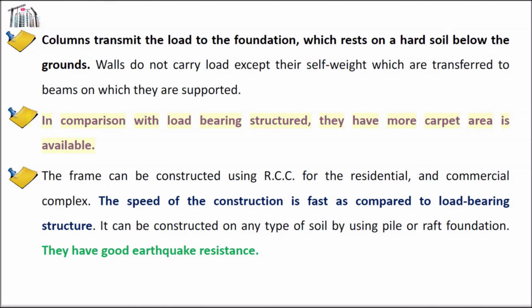In comparison with load-bearing structures, more carpet area is available. The frame can be constructed using RCC for residential and commercial complexes. The speed of construction is fast as compared to load-bearing structures. It can be constructed on any type of soil by using pile or raft foundation. They have good earthquake resistance.